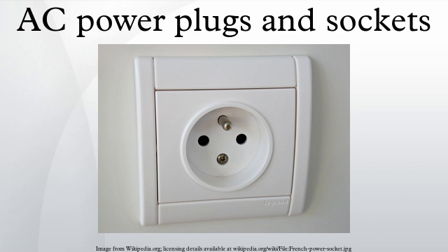In Chile, 10A Magic connectors are commonly used for computer laboratory power networks, as well as for communications or data equipment. This allows delicate electronics equipment to be connected to an independent circuit breaker, usually including a surge protector or an uninterruptible power supply backup. The different style of plug makes it more difficult for office workers to connect computer equipment to a standard unprotected power line, or to overload the UPS by connecting other office appliances.